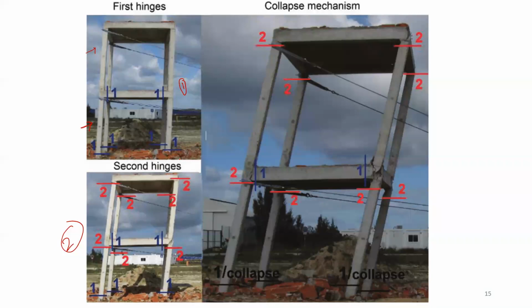Now, the deflection happens when the extreme fibers reach their ultimate load or their yield stress. In the third figure, what is happening is due to the formation of the plastic hinge. That means when all the fibers in the concrete or in the steel reach their ultimate position or ultimate load, then there is a formation of plastic hinge.